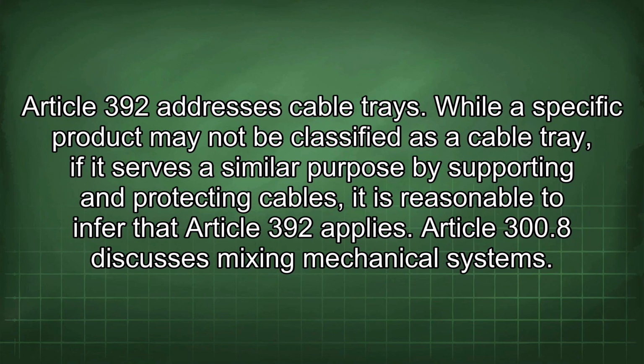Article 392 addresses cable trays. While a specific product may not be classified as a cable tray, if it serves a similar purpose by supporting and protecting cables, it is reasonable to infer that Article 392 applies.